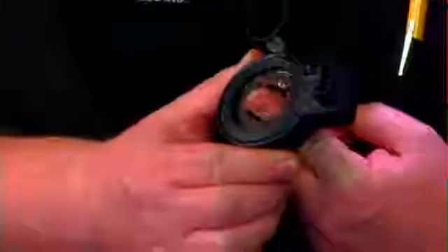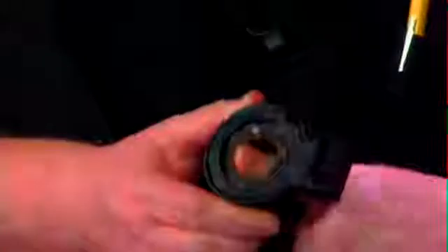He's referring to something called a steering angle sensor. A little device like this that goes typically in the steering column, so the steering shaft and the column goes through it like that. And as you turn the steering wheel, this sensor, either optical or in some cases a couple of potentiometers and a little switch that opens and closes, tells a module not only where the steering wheel is pointed, but also how fast it's being turned, and in some cases the torque you're putting on the steering wheel as you turn the wheel. That's very important to know.